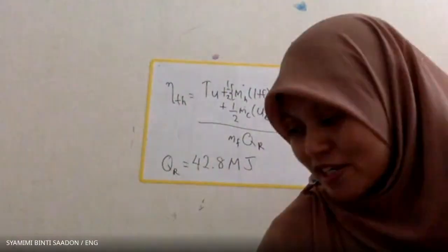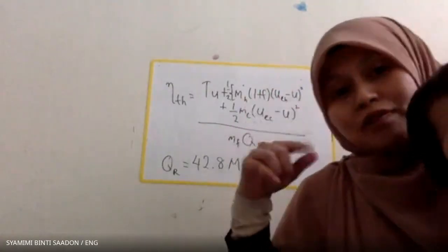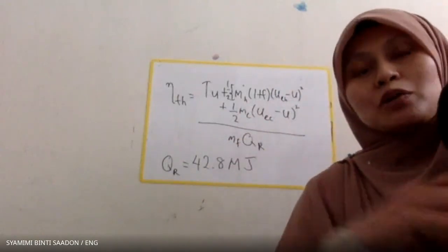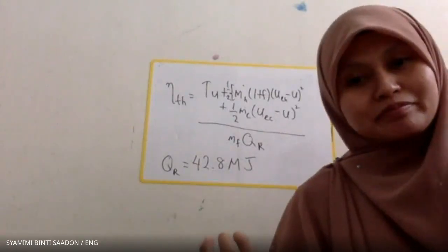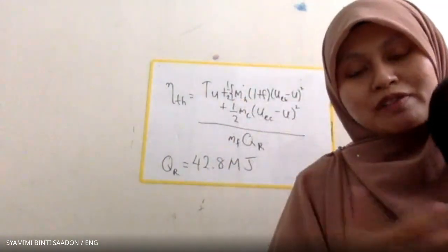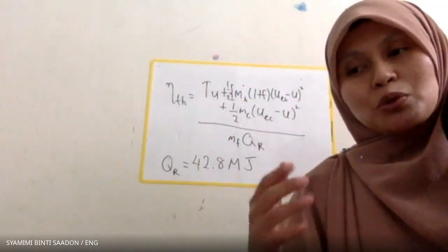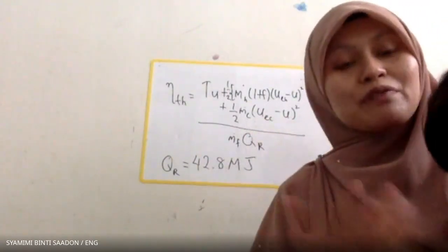Doctor, what is TSFC again? Just now, the answer or what? The answer is 0.031, I have written here. Yeah, I mean the meaning of TSFC. Okay, m dot f over thrust, right? It means that in order to produce 1 kilonewton of thrust, how much fuel do you need? So it quantifies the fuel that you need. Oh, okay, all right. Thank you, Doctor.